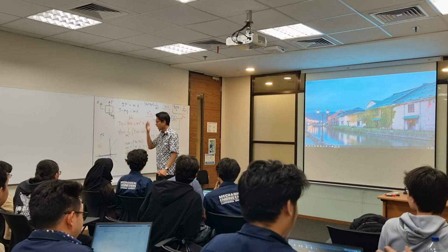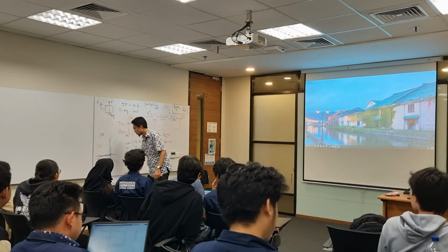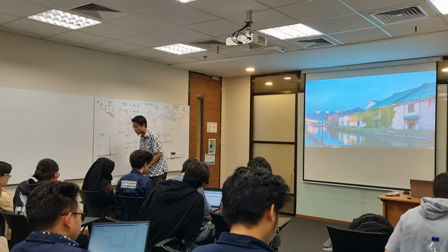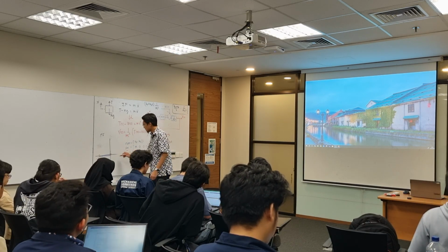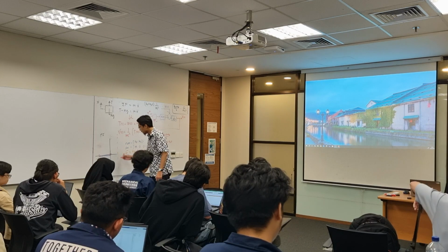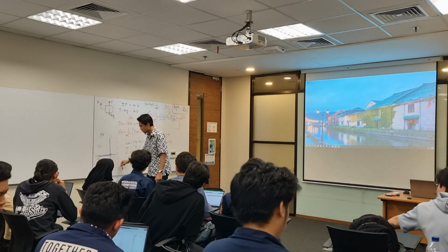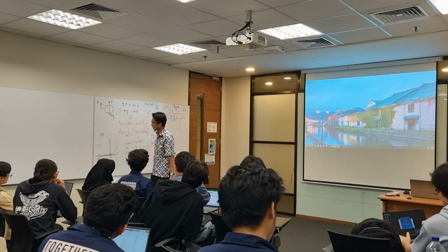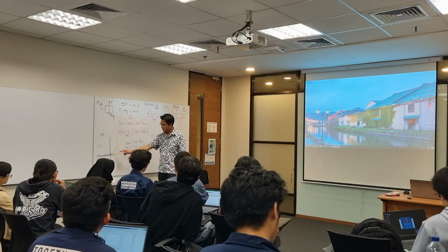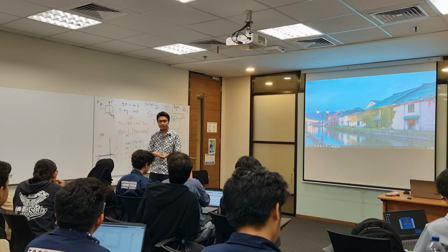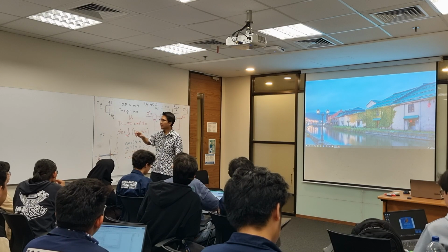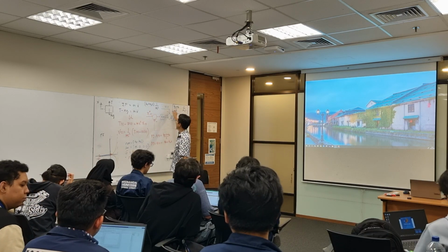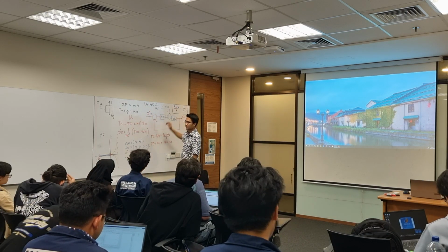Okay. Asymptote is 2, right? Sorry, I made a mistake. We have 3 asymptotes. So one is 90 degrees, the other one is 270 degrees. So it turns out it goes like this. I mistyped the asymptote. What is an asymptote? It is the direction where your closed loop pole will go if you increase the gain of your system.